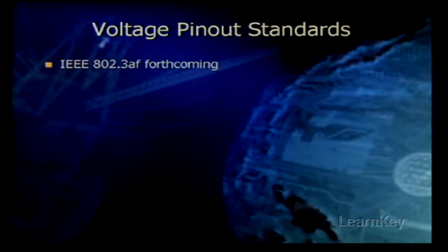Right now, with the 802.3af standard, the IEEE has standardized on the use of 48 volts DC as the injected PoE voltage. The use of this higher voltage does reduce the current that flows through the Cat5 cable and therefore reduces the load and increases the Cat5 cable length limitations. Where the maximum cable length has not yet been a major consideration, some other vendors have chosen to use 24 volts DC or even 12 volts DC instead of the 48 volt DC standard as their injected voltage.